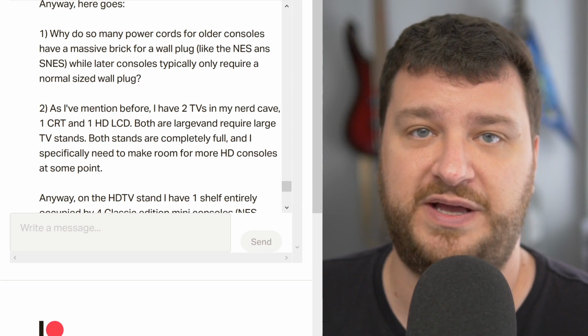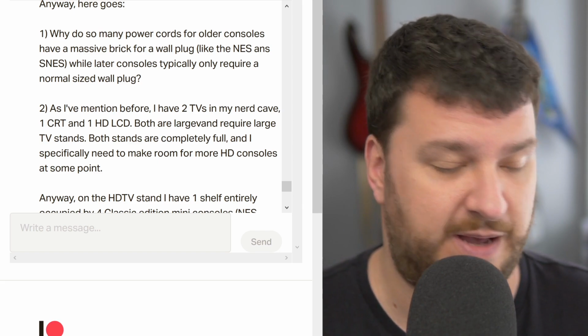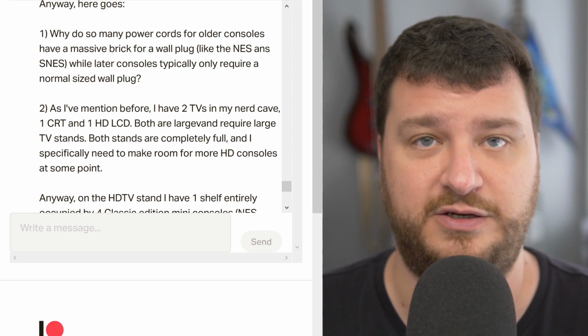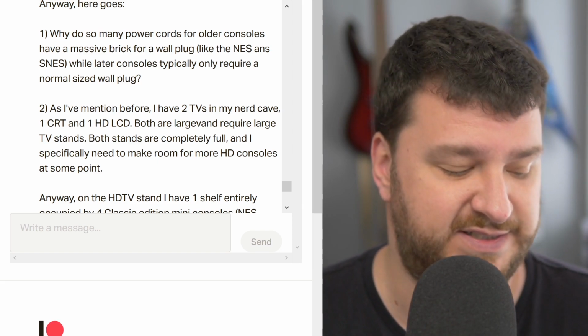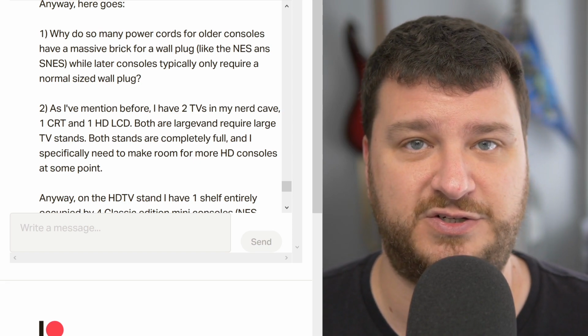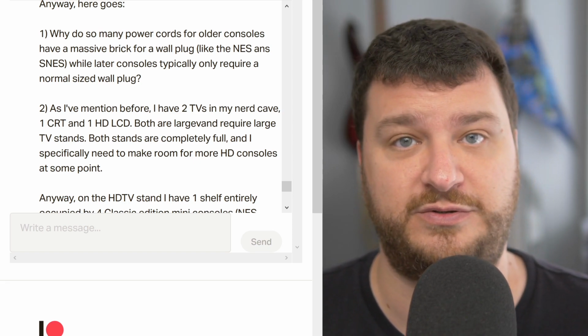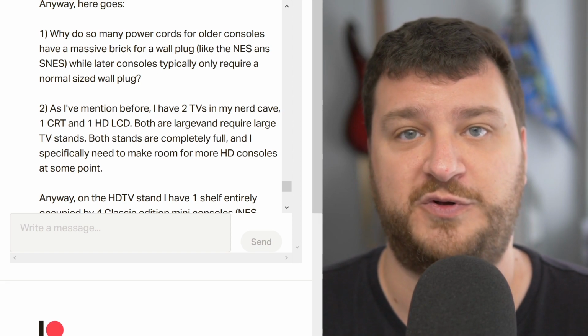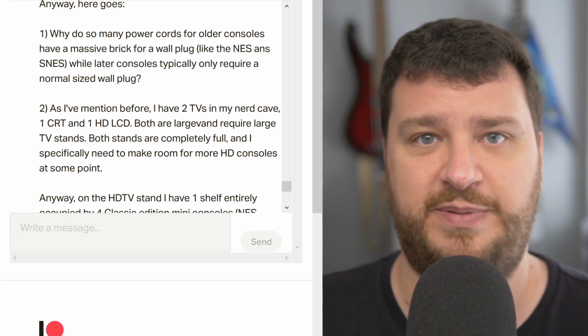Because if you have a power supply that's aging, yes, you could pop it open. Some you can, some you can't. You could replace the capacitor, hope that fixes it. But I'm just a fan of getting these triads, and you can get them internationally too, so you could buy one and use it for multiple different AC power sides.